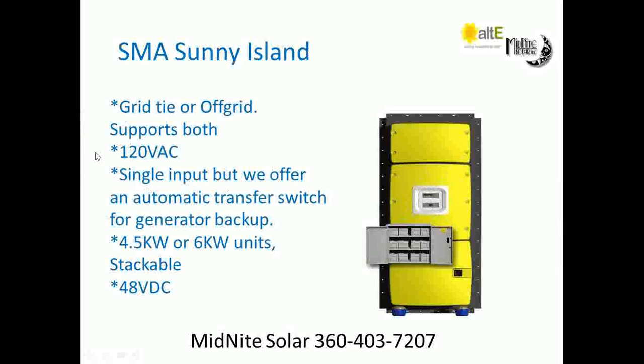It's fast enough that you may or may not even see just a little flicker in the lights when it happens. So it's pretty seamless. Computers will not reboot, nothing like that. But it's not truly running in parallel. In other words, the question was synchronous paralleling or actual transferring.